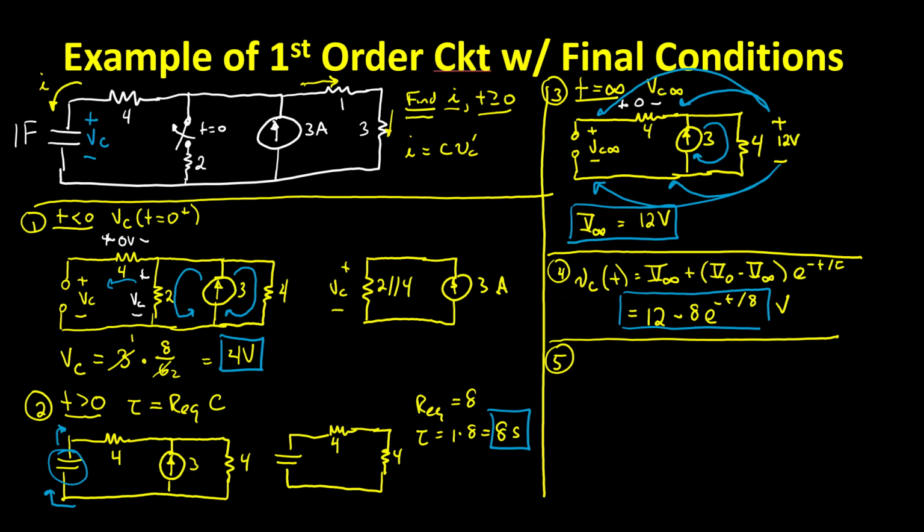A lot of different ways. There's smart ways and there's not so smart ways. Don't think that this voltage across the capacitor has to be the same as the voltage across the resistor so you can use Ohm's law. It's a completely different voltage across the resistor. The only thing that's the same is the current. But in this example, we can use the relationship I equals C dV/dt, that basic relationship of a capacitor, to find out what our I is.